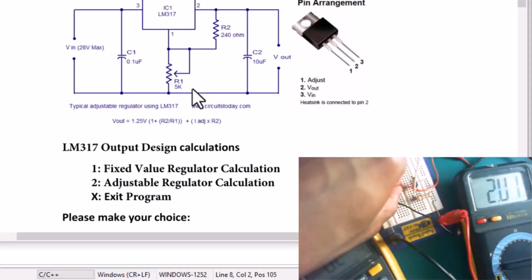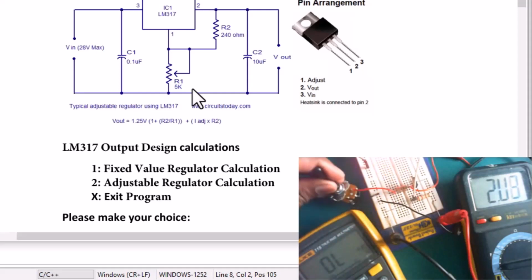So when I put it back, there was a swing. I did disturb it, so I have to change it again so that it can have 5 volts. Right, so this is how the LM317 voltage regulator works. You have an input voltage and the output can be regulated via the adjust, or you can put in a fixed resistance and that will give you a fixed output voltage.